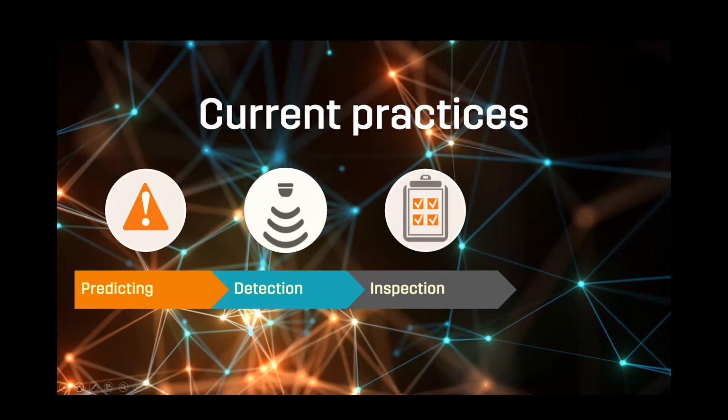A couple of other technologies that we've seen as well are around the low frequency electromagnetic techniques, and again, they've been around several years and are being applied for vessel and pipework inspections. And again, there has been recent success, including the deployment via scanners and robotics. So it's another technology that we are monitoring and reviewing how that progresses.